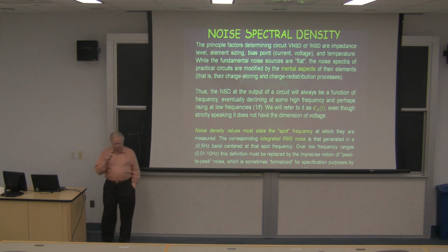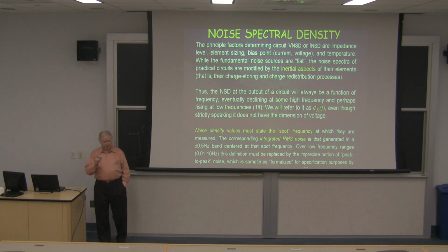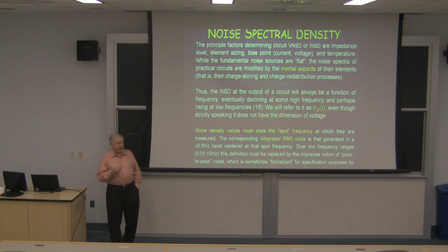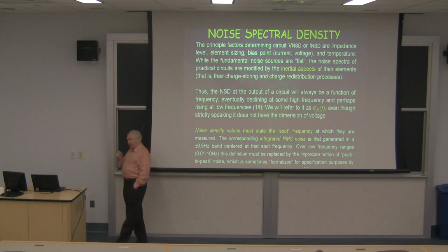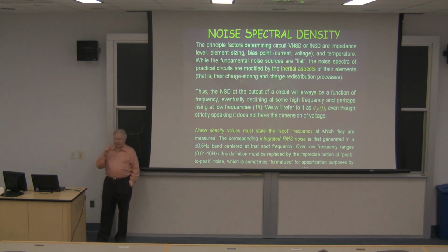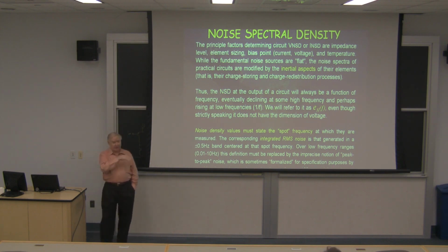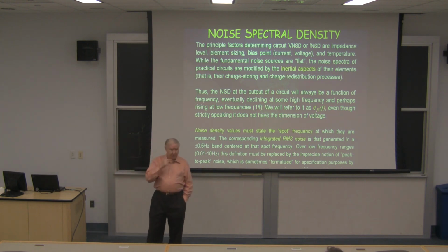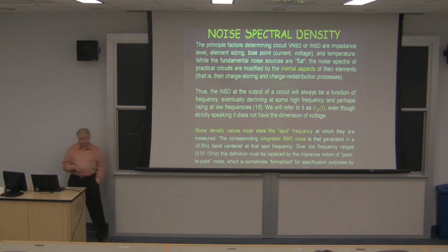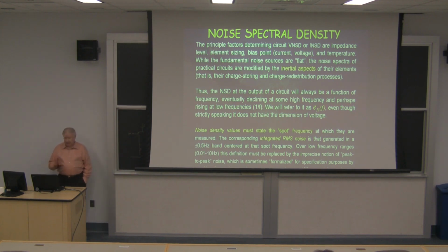It therefore follows that when we speak of a spot noise, you'll sometimes see a noise figure of 1 dB at 2.4 gigahertz. Well, this illuminates the practical fact that the noise spectral density measured in a 1 hertz bandwidth, that's per root hertz, or in a narrow bandwidth, actually varies across the frequency band. If we look at the total integrated noise, it's defined by the bandwidth of the entire amplifier or system or whatever it might be, but usually we're operating things such as radio receivers at single frequencies with rather narrow bandwidths. So noise figure is sometimes a bit misleading. I've seen ads for transistors that say noise figure of 1 dB, and it doesn't mean a thing because it all depends upon how you use the device. What they really mean is that under the best conditions you can get this thing to work down that far. So there is this difference between integrated RMS noise and measurement at a spot frequency with a 1 hertz bandwidth.